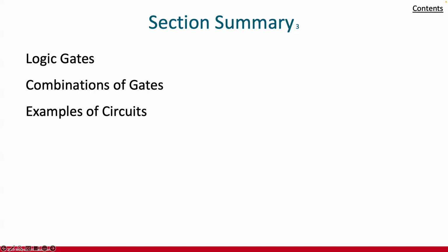Each type of gate implements a Boolean operation. In this section, we will define several types of gates. Using these gates, we will apply the rules of Boolean algebra to design circuits that will perform a variety of tasks. The circuits that we will study in this chapter give output that depends only on the input and not on the current state of the circuit. In other words, these circuits have no memory capabilities. Such circuits are called combinational circuits or gating networks.